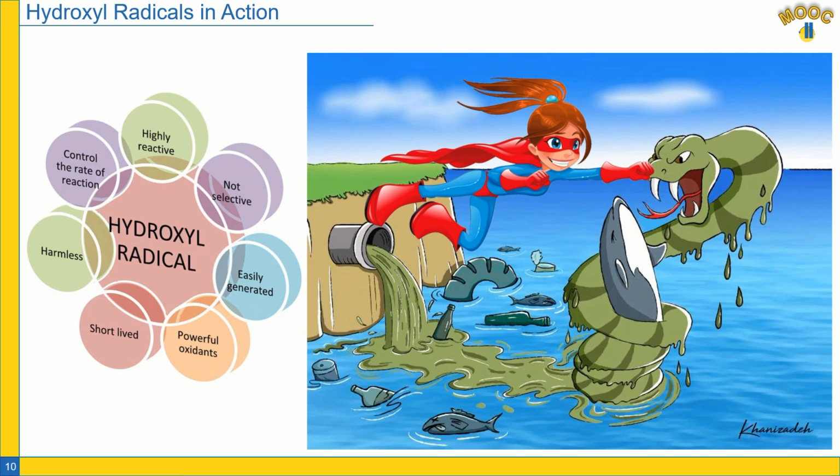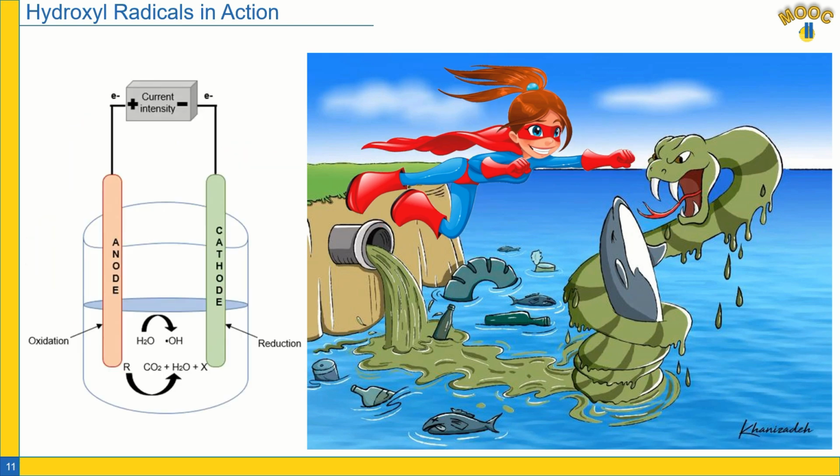By having these hydroxyl radicals, we can attack the organic pollutants that we have in any type of water, to oxidize them and produce simpler molecules. So how does it work? When you have hydroxyl radicals, as I said, they are highly oxidizing. They attack the organic pollutants, and at the end you produce CO2 and water, and you decompose all those organic pollutants.